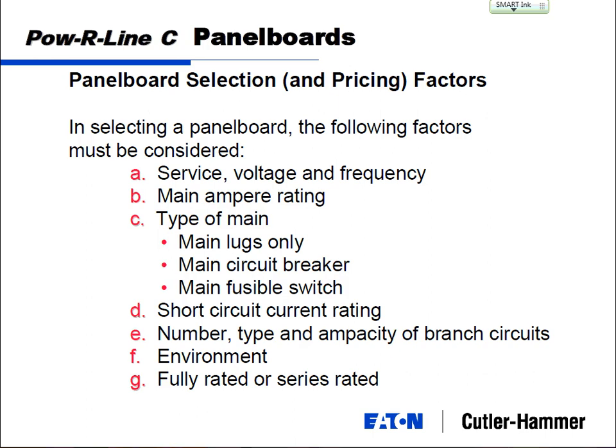And the other thing is, if you've got a fuse and you have a fault condition, maybe you accidentally stuck a screwdriver in a light socket and tripped the main breaker. Okay, if it's a main breaker, that's fine. My mistake, I walk back up, I reset the breaker, everything comes back on. If it's a fuse, I walk back up, I have to change the fuse before putting things back on.